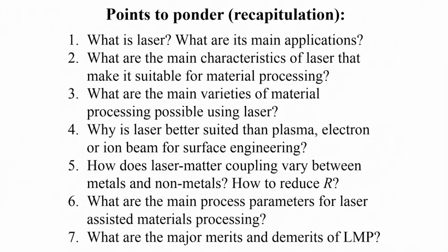Everything is good about laser, but the capital cost is very, very high, and you also need a fair amount of skill to make correct use of laser for various materials processing. But on the other hand, the biggest advantage is that it's an extremely fast process. Another major demerit is that the beam size is typically on the order of millimeters or less than a millimeter, whereas the bulk solid you're talking about, in terms of volume or surface area, is much higher than the size of the beam.